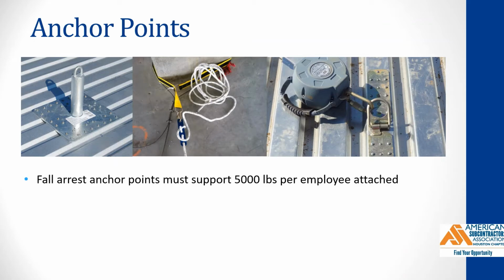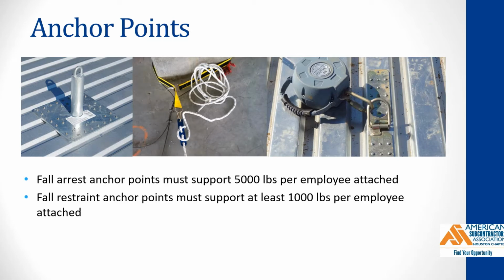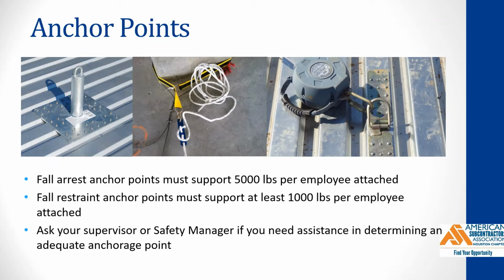Fall arrest anchor points must support 5,000 pounds per employee attached. Fall restraint anchor points must support at least 1,000 pounds per employee attached. Ask your supervisor or your safety manager if you need assistance in determining an adequate anchorage point.